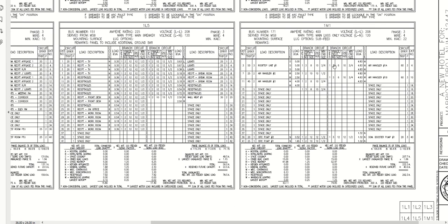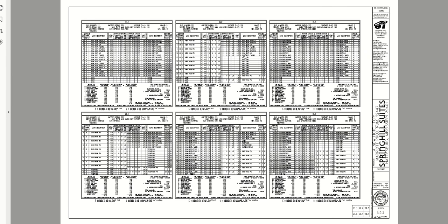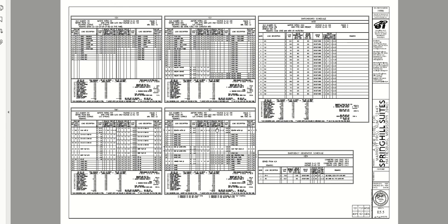Looking at some other panel schedules, these are all guest rooms. Here we have just mechanical equipment, so you see we have HVAC loads and space heating. Come over here, we have non-continuous, we have receptacle loads, lighting loads. So again, just every kind of load you can think of, and you can see how they're handled in the load summary down here. And so again, we just have panel after panel, same thing, doing the calculations, adding up the loads, applying diversity factors, and 3rd floor panels, 4th floor panels.